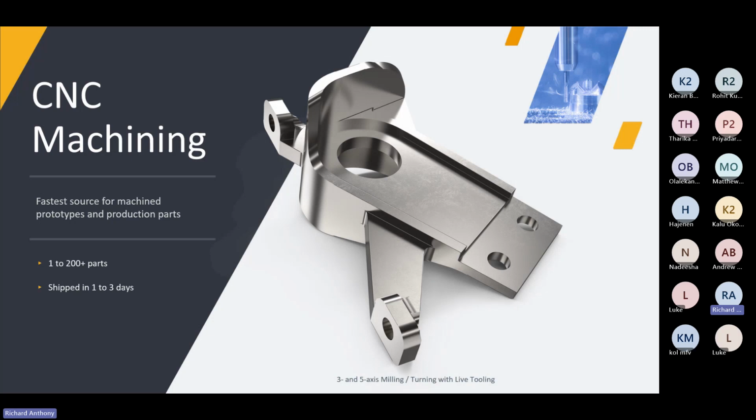The way our online system works is you'll upload your CAD file and our analysis software will work out how much of the part can be machined. So we have a fixed cutter set. Things have to be more limited to offer the fast lead times that we do. So it's not uncommon for there maybe to be some small radiuses or a deep slot that we can't access with any of our cutters in our cutter sets.